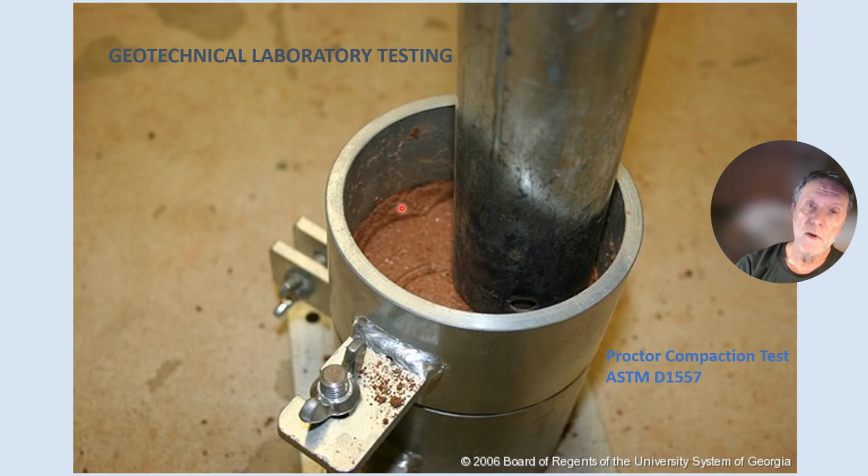So you want to do, for any specific type of soil, you want to do this at least 3 times. Once with a soil on the dry side, once with the soil near optimum moisture, and once with the soil at a wet side, more saturated moisture. That way you get a curve, which I'll show you a little later in a subsequent slide.